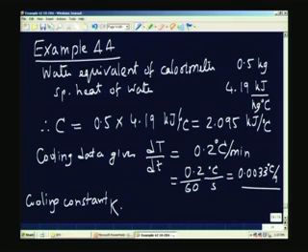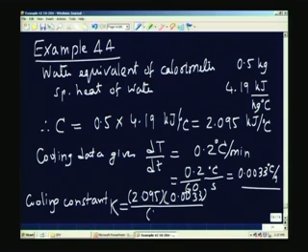This is your capital K, which will be C dT by dt, therefore 2.095 multiplied by 0.0033 divided by (T minus T1). This data says that T was 22.7 when the slope was calculated, minus 20, and this will be your K, which comes to 0.00259 kilowatt per degree Celsius.